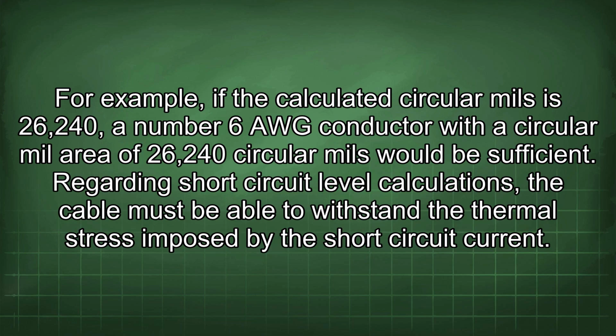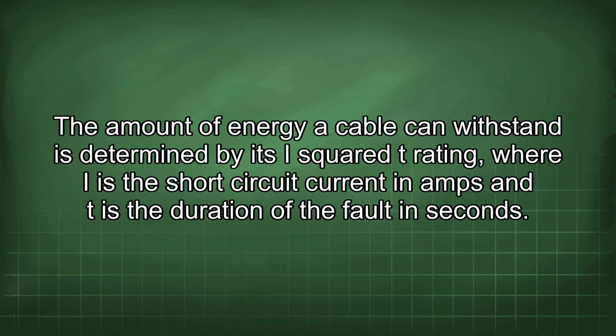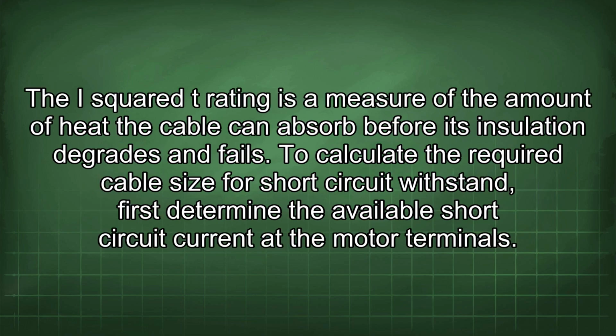Regarding short-circuit level calculations, the cable must be able to withstand the thermal stress imposed by the short-circuit current. The amount of energy a cable can withstand is determined by its I²T rating, where I is the short-circuit current in amps and T is the duration of the fault in seconds.